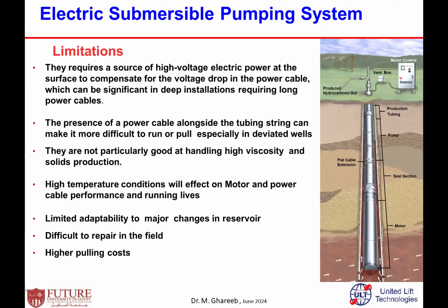It's also about the capability to match a change in well productivity. It's not easy, because this pump must be run within a certain range of flow rates. The flexibility to change is not as high as with a rod lift system or some other artificial lift.